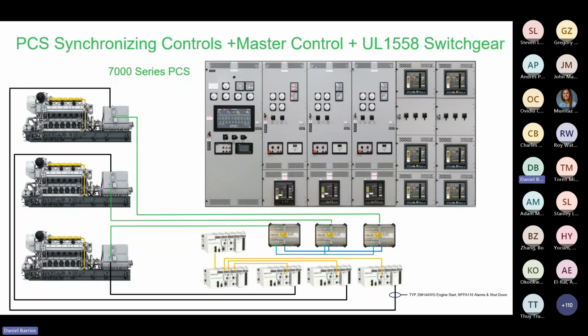As you look in each of the generator sections, we also provide you a generator PLC. Should you lose your master PLC, the generator PLC is still in control and will perform functions that need to be done to put the generators online safely. Above that, you notice again, we're using the digital synchronizer and load control. And in this case, we are doing a duplicate landline. Should you lose one of the landlines, the second one will immediately pick up. And again, you will not have any loss.